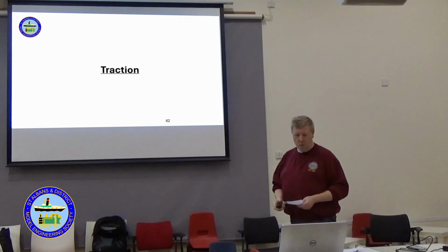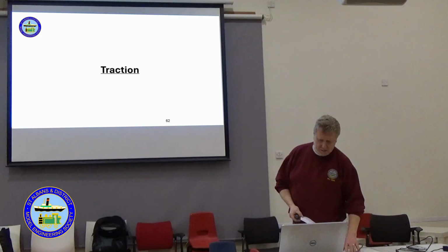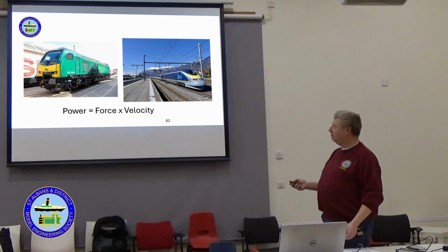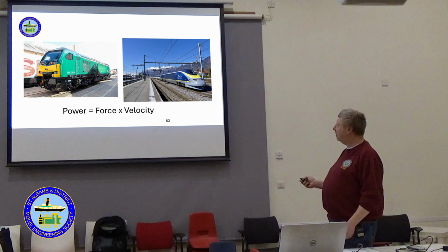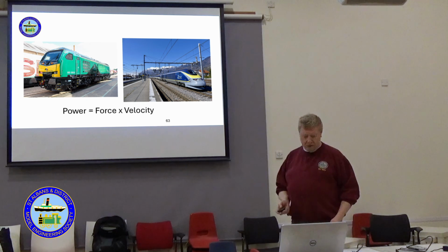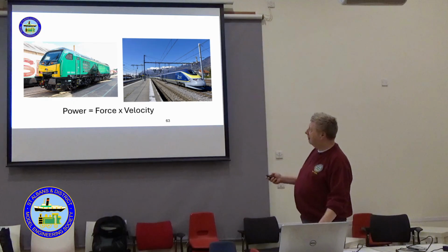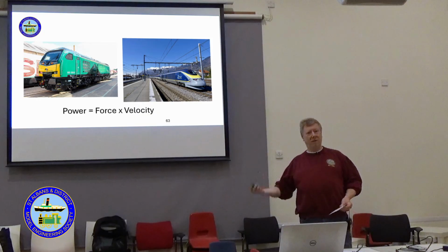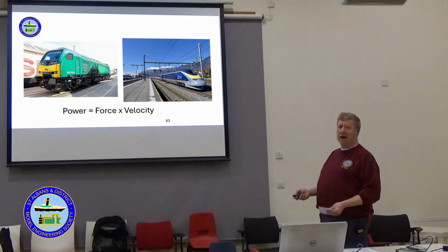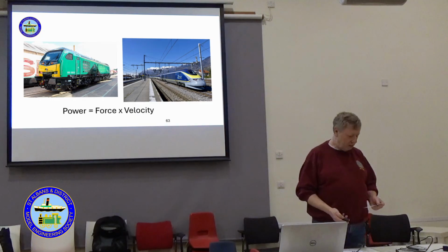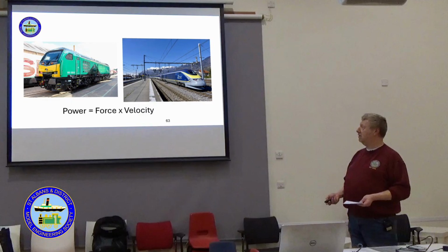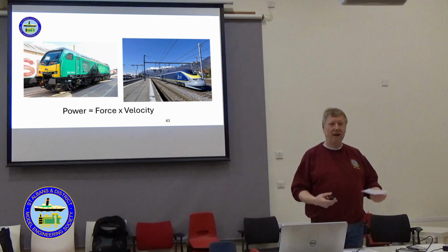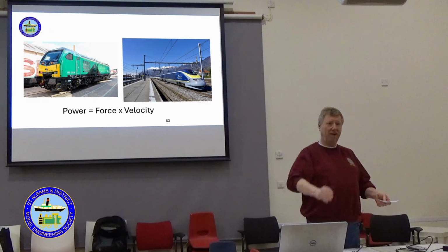Right. So all modern locomotives use traction motors now. As Mick and Mike told you a while ago, they're either diesel electric or they are direct electric, which gets the power through pantographs and catenary wires. So these things have a diesel motor that drives a generator. That generator generates electricity, which drives a traction motor. This just sucks electricity straight in and drives a traction motor. The benefits of traction motors is there's no gearbox. It's just a motor. It's like an electric car. There's no gearbox. You squeeze the accelerator and it goes faster. Take your foot off, it goes slow.